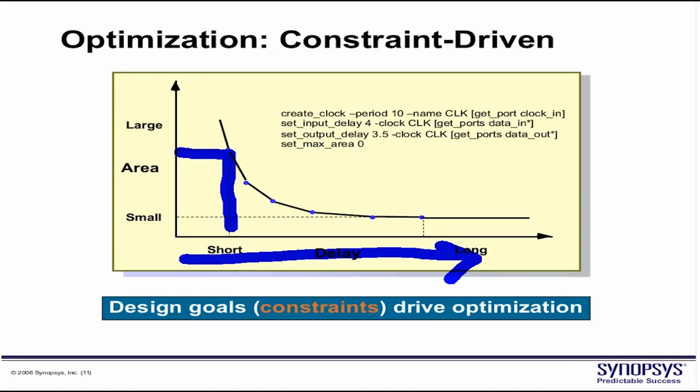Even if we talk about the cell design, the cells which are faster and have better drive strength are always bigger in area, because again their W/L ratio will be high. They'll probably have inbuilt inverter or buffer stages. So these two things, area and delay, are always fighting each other.